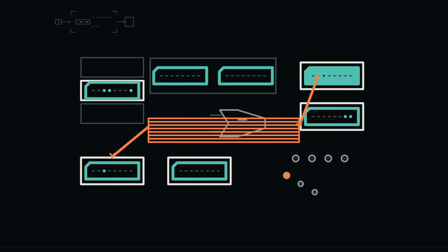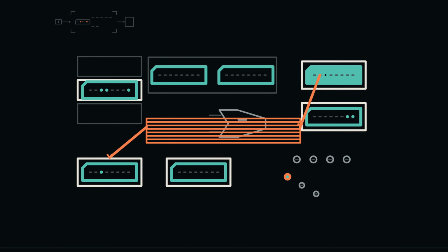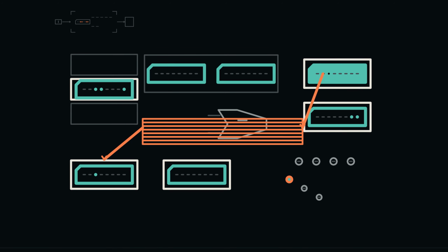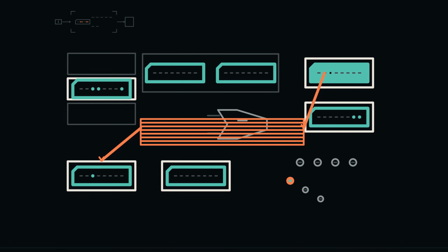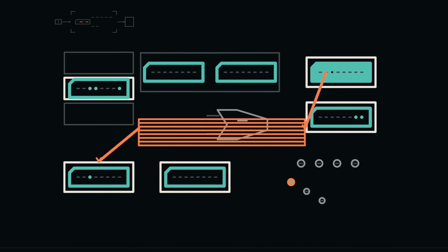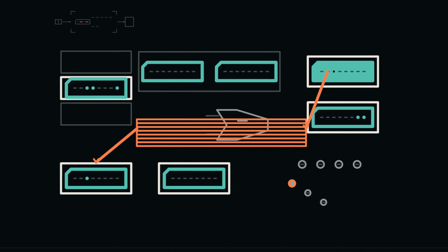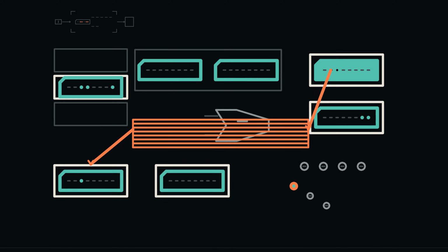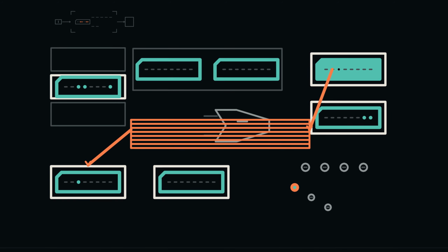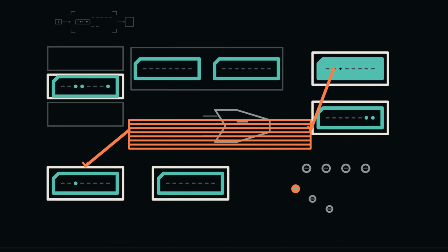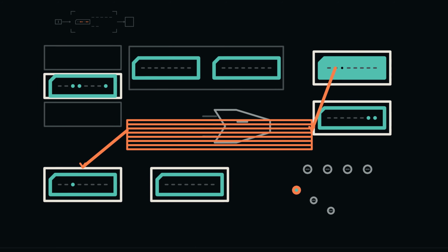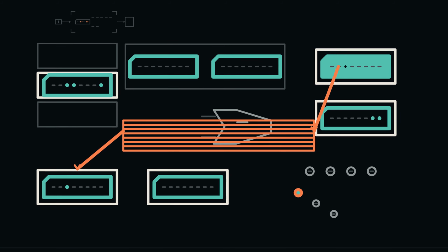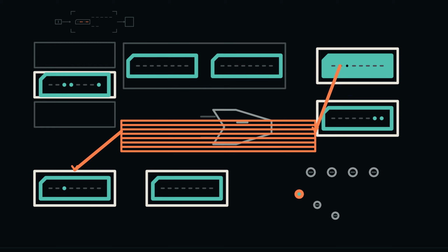Before cycle 0, PC is 20, MAR holds its reset value, the bus is inactive, and no memory event is committed. In fetch 0 address, PC drives 20 onto the bus and MAR is enabled. Predict the post-edge ledger. MAR becomes 20. PC remains 20. Memory has not yet been read. Instruction register 0 and instruction register 1 remain unchanged. The controller records that the address has been latched and moves to the read state. One edge has established which memory location matters. It has not fetched a byte by implication.